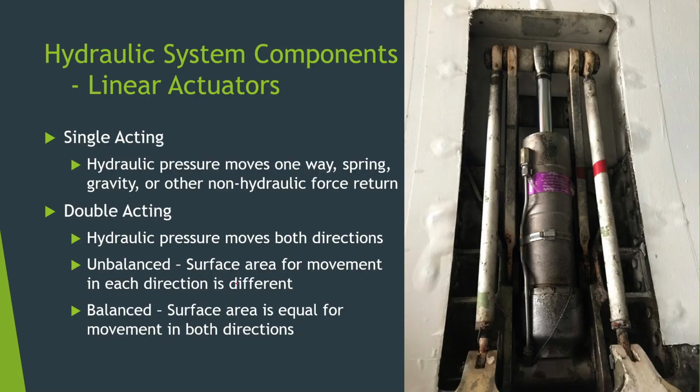So here's that cargo door actuator. Fluid ported in the bottom of this actuator. I don't know if I draw on here. Does this show up on yours? Hey, it does. That's much easier. So when fluid's ported in the bottom, it's going to have a lot larger surface area than the fluid that is ported into the top up here.